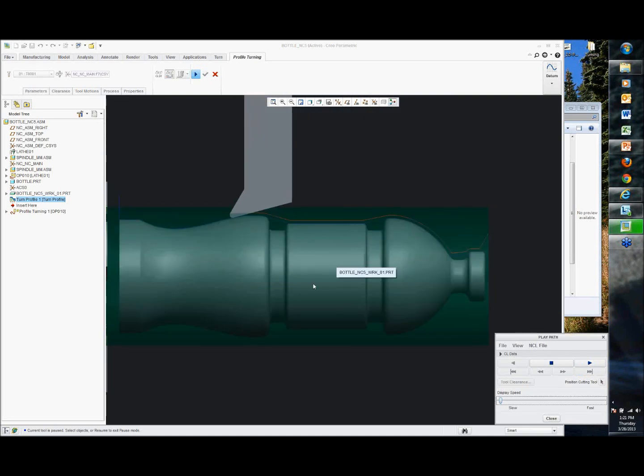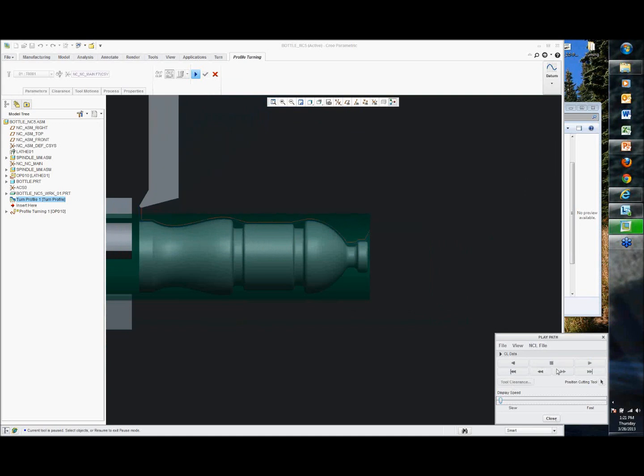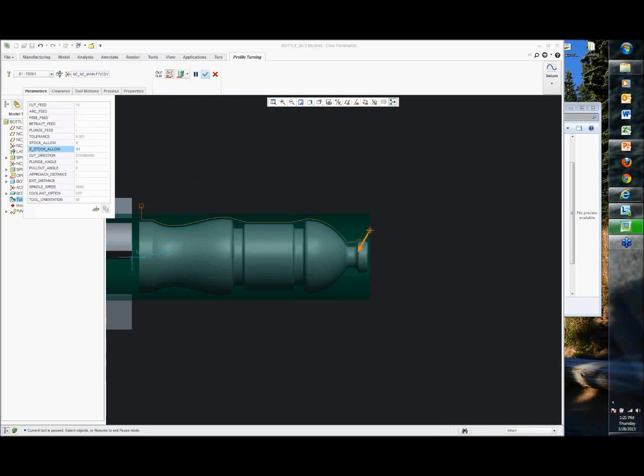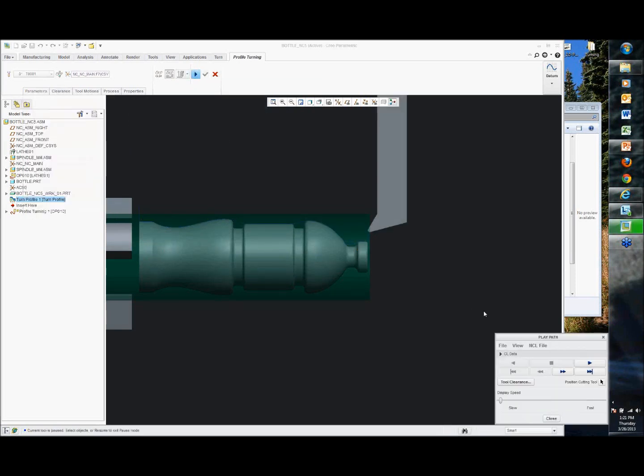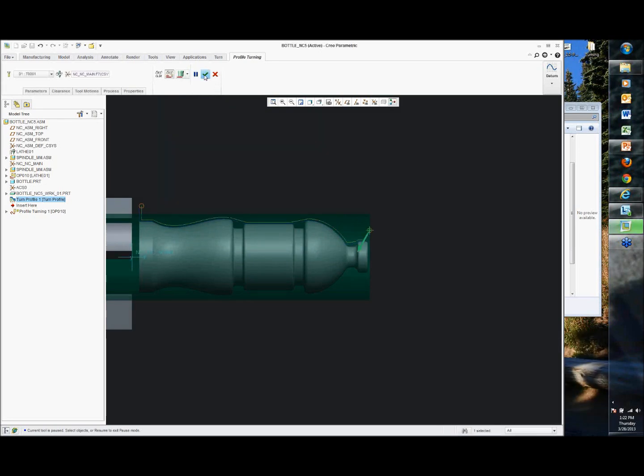And then I can come back with a groove afterwards. Right? Maybe change the angle there or get a little bit more of a standoff clearance here. So maybe go back in and say instead of 5, let's go 10. Try one more time. So I try to use multiple tools to see what's going on, and it might be that this is not a bad way of seeing what's going on, but Vericut might give me a little bit more view of that. So get done with it.